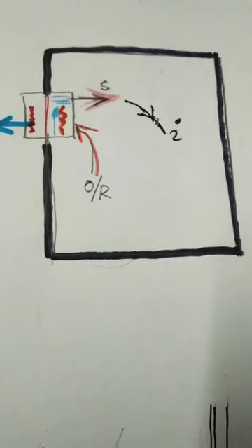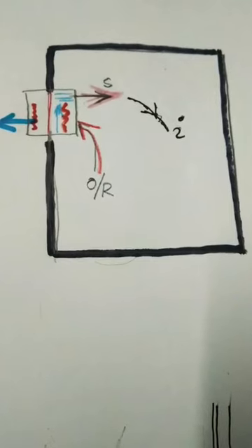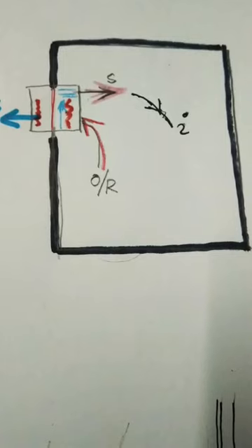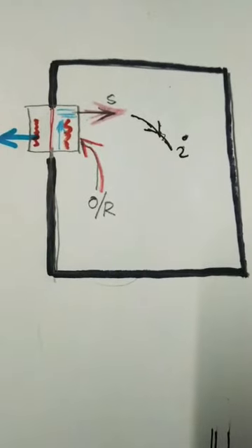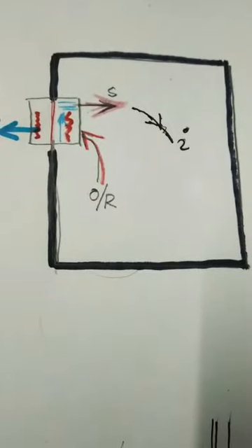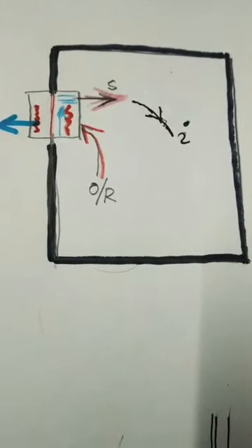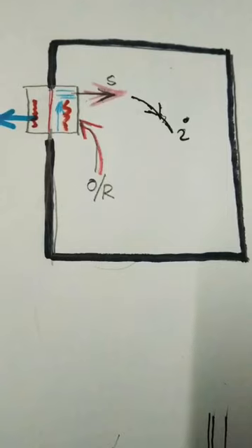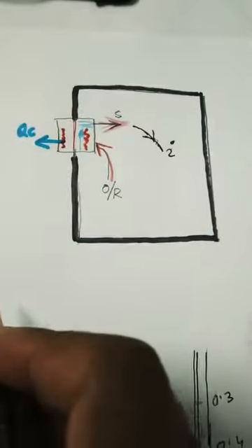parameters. The parameters are being frozen, and it has been found that there is a certain wall thickness, a certain orientation of north, south, east, west, and a certain amount of load on this particular room. Any room can be identified in any designed, built, or proposed structure, and then one can understand that this particular room is for a certain purpose, and there is a certain amount of load in the form of sensible heat and latent heat, which I have explained earlier. And once we come to know these two things, then we define what is known as room sensible heat factor.